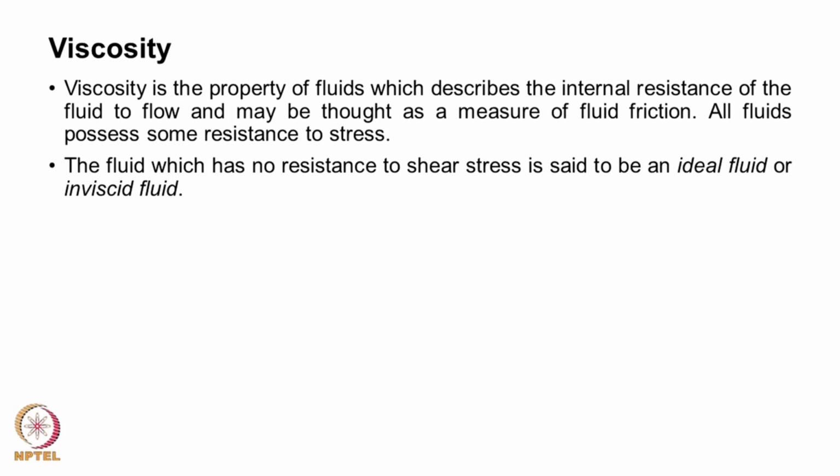Then that inviscid solution can be taken as an initial condition for the subsequent viscous calculation. This stage by stage numerical simulation is helpful to overcome numerical difficulties.